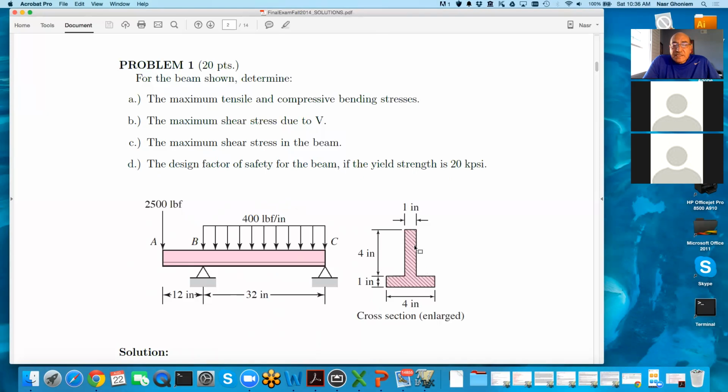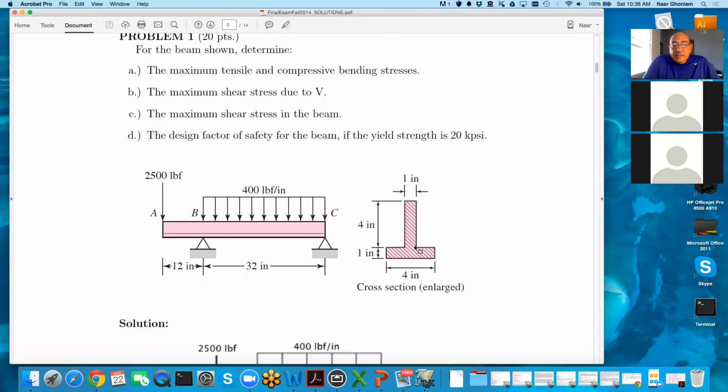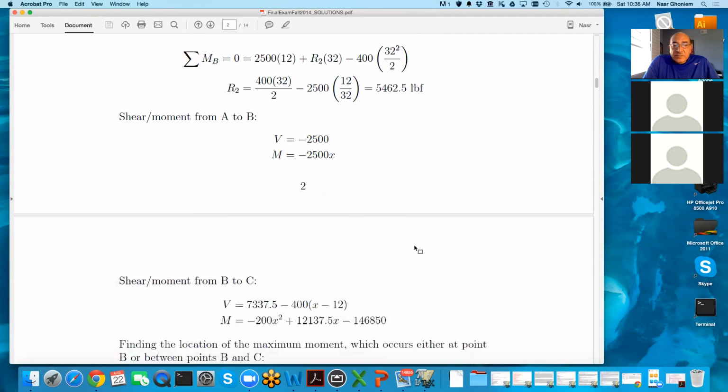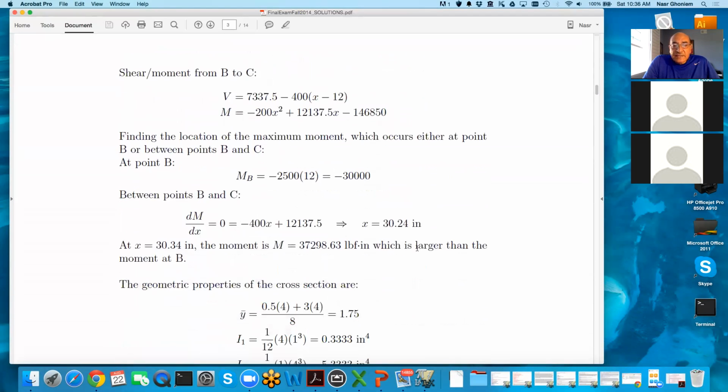Variation could be a composite beam, and a composite beam, we didn't really dwell much on it, but there's also kind of concern about shear failure in composite beams. So it depends on how the question is posed, you look at it carefully to see whether you have to address shear failure by itself or shear plus tension in the form of von Mises. Depends on the final answer.